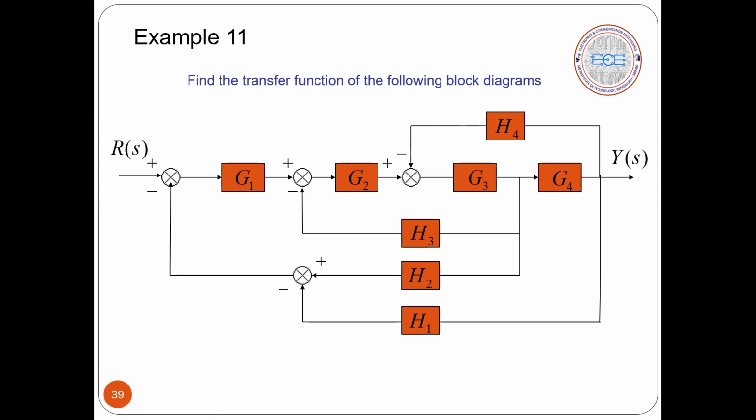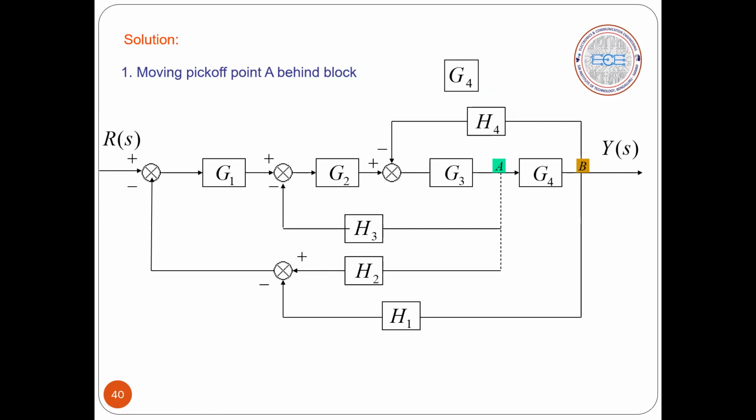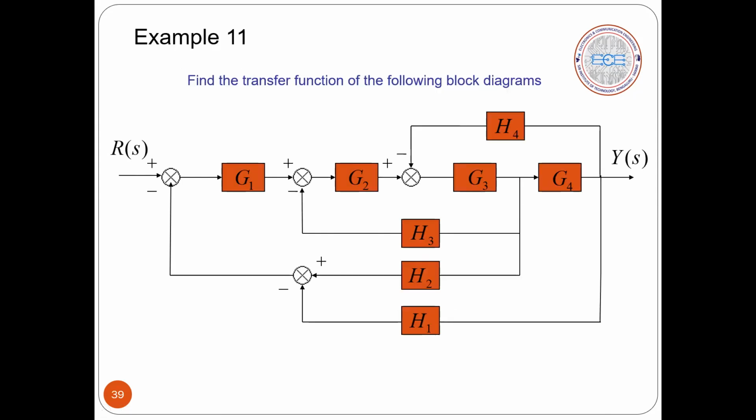Okay, next. So, sorry, we have a block diagram for which we have to find the transfer function. Okay, this is also a little complicated because you have so many summers here in the second line. If you take this as the first line, you have a summer in the second line. You have to simplify this. Okay, so just look at the block diagram. Shifting this takeoff point will help us in moving ahead. Correct, we can move ahead by just shifting this takeoff point.